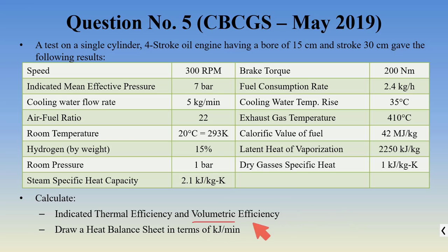The first thing is the volumetric efficiency. In this sum, you have to calculate the volumetric efficiency of the engine, so we will see how we do that. And the second thing is that we have to draw a heat balance sheet in terms of kilojoule per minute.